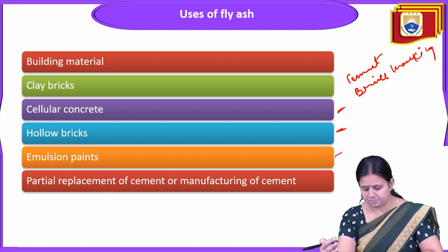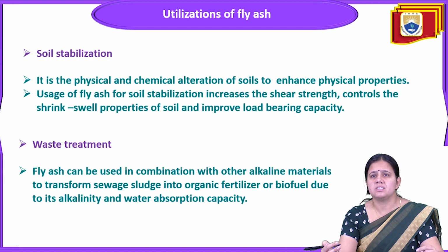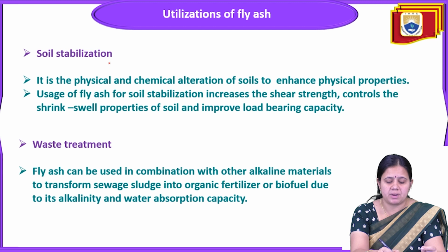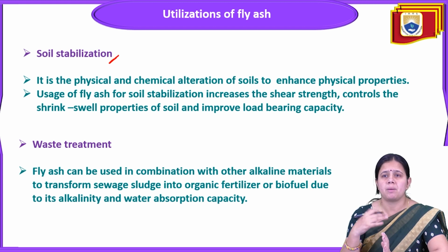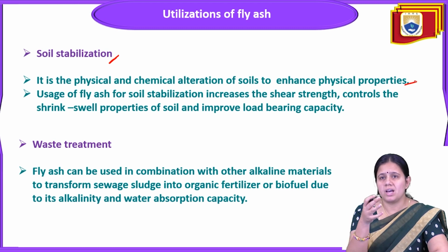So these are some of the sectors where this fly ash can be utilized. Now next, it can be utilized in soil stabilization. Stabilization of soil is the physical and chemical alteration of soil to enhance its physical properties. Soil with fly ash is having high bulk density.